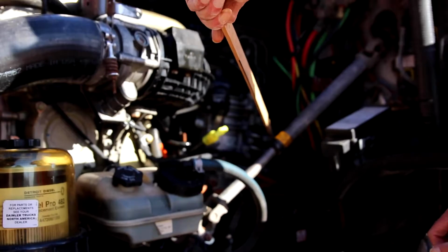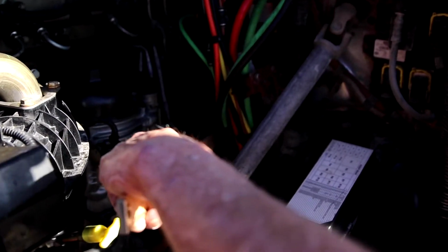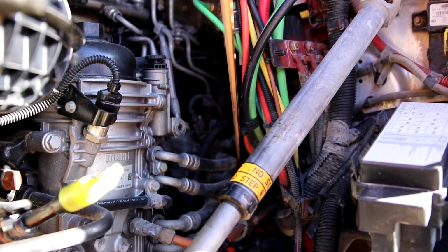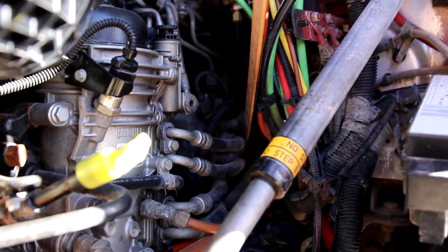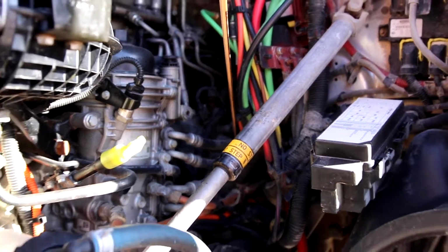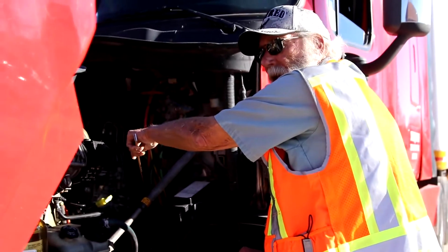Moving towards the inside to the rear of the engine. Extremely hard to see is your air compressor. It is really buried in there. You need a flashlight to see it. It is mounted securely to the vehicle. There are no audible leaks. It's got air. And it is gear driven.